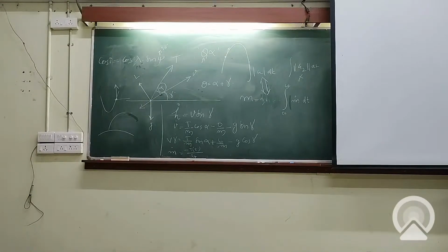Now we have come to the terminal phase. Terminal phase, the last stage of the launch vehicle, is where the injection of the spacecraft happens. Now, if you see in all the lower stages, we don't really impose this concept of optimality. Mostly, the first stage will be a solid stage, where you cannot have a mass advantage. Right? Whatever fuel that you have loaded has to be spent.